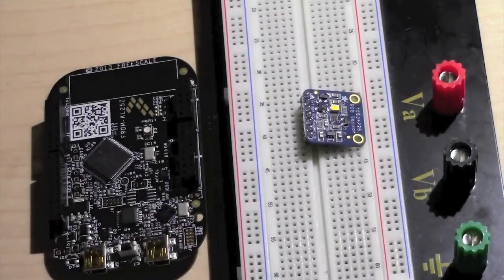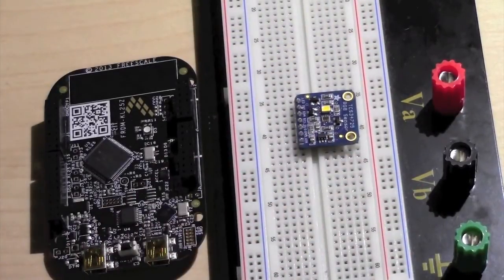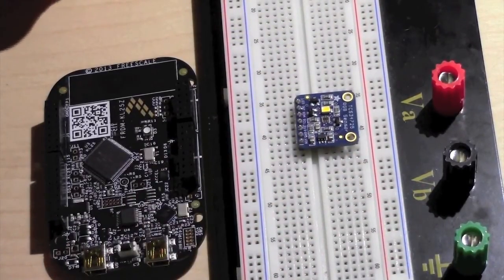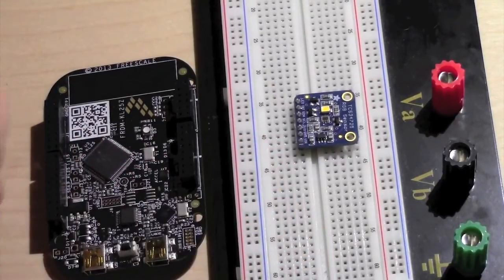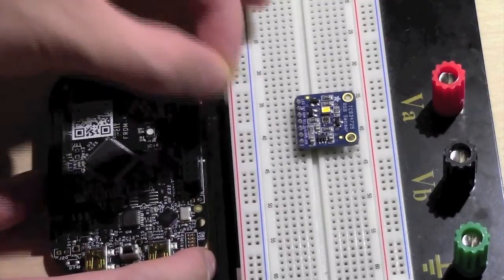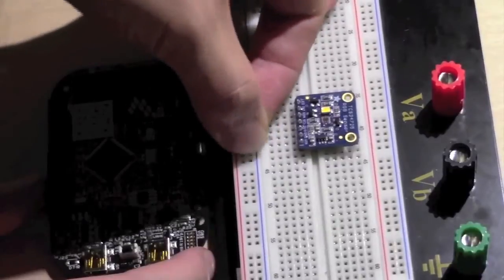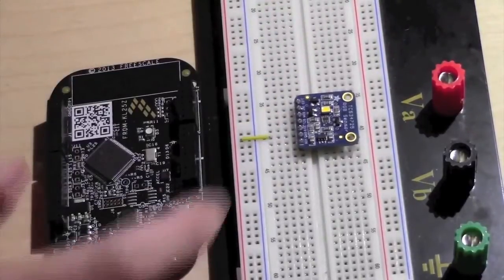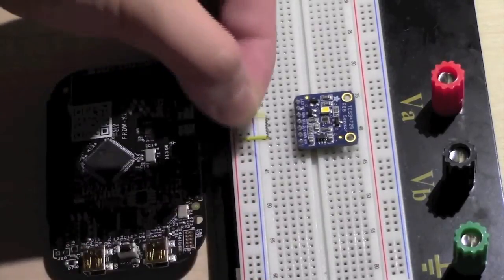All right, so we're going to go ahead and hook this up onto the breadboard. I'm just going to put the color sensor onto the breadboard itself. Just stick it in there. Then we're going to connect 3.3 volts to the power line. Later we're going to be using the microcontroller power wire and connecting it over here. So we're just going to connect this to the power line, 3.3 volts. I'm going to connect the ground pin on this to the ground rail right here.